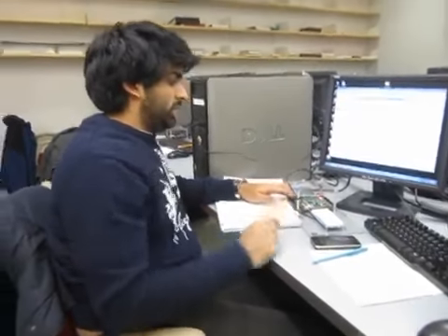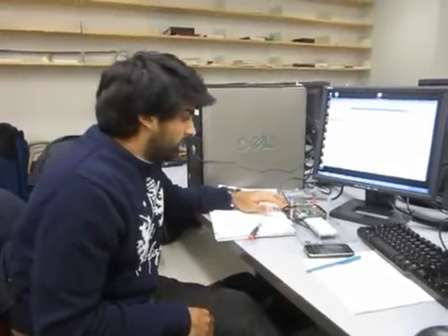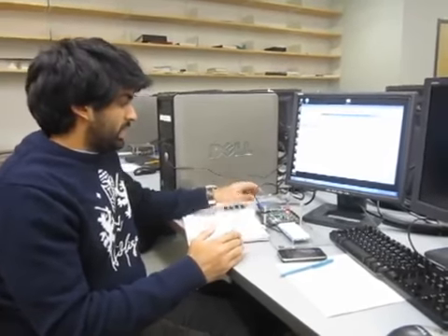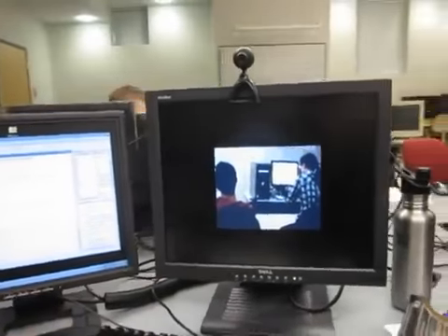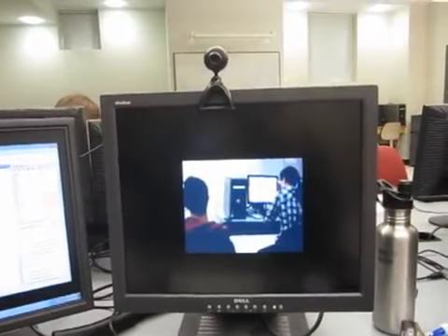So once the signal is received by the FPGA over the UART, it is loaded into the block RAM, where it is stored until the image is fully transferred. After that, it is sent over the VGA to our monitor, where you can view the live streaming video.